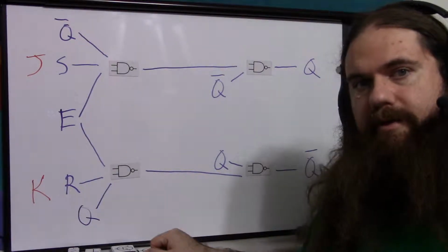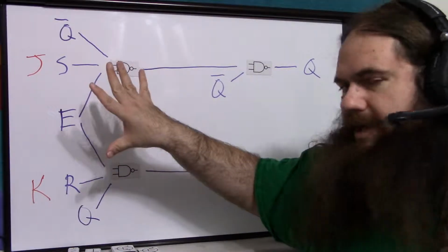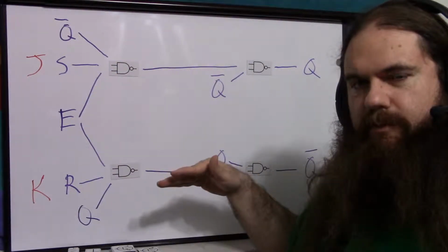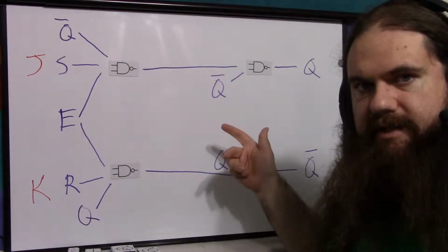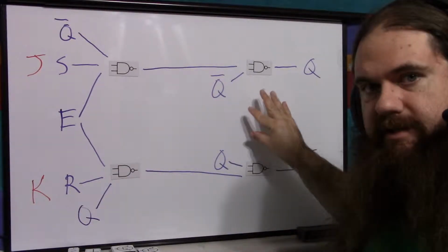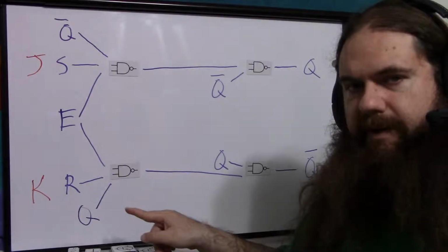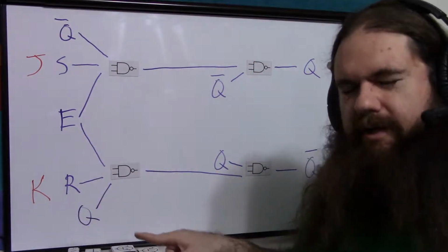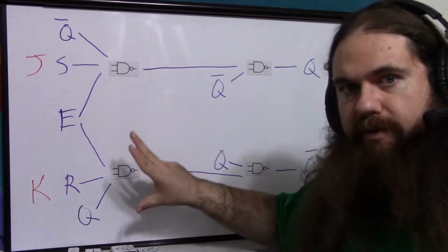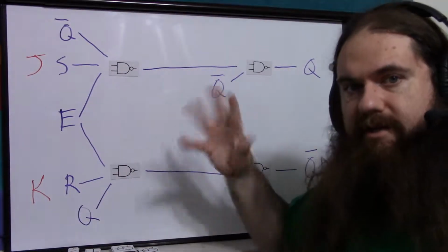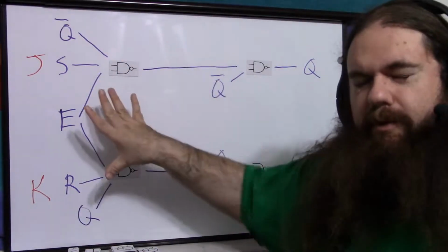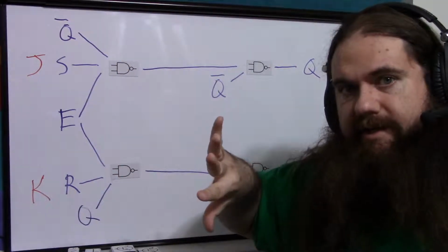And furthermore, think about what actually happened. When we give it both signals, it ignores the one that does nothing and uses the one that does something. So it prevents the invalid state of giving the latch itself both signals, but it's always going to be the one that does something. If we're set, and we say both set and reset, it's going to reset. If it's reset and we give both set and reset, it's going to set. It toggles. We have now made a thing that toggles. Every time you give it both signals, it flips. Whatever it is, it flips.